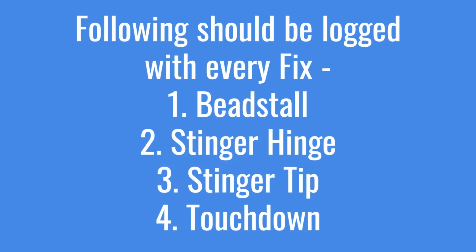So what is our job as a surveyor? As soon as the barge movement is completed and a new segment of pipe is being aligned at the bead stall before welding, you take a position fix. In this position fix, the following data will be logged. That is your bead stall position, your stinger hinge position, stinger tip position, and most importantly, the theoretical touchdown position.